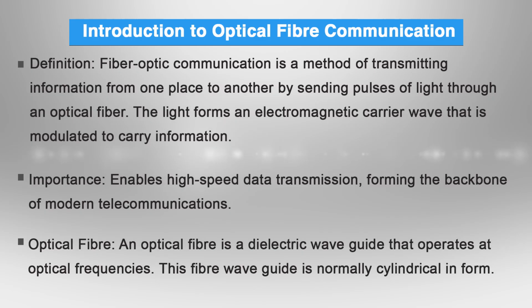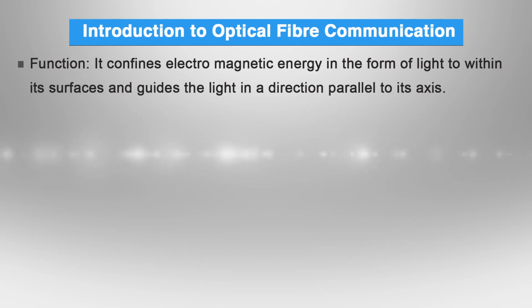An optical fiber is a dielectric waveguide that operates at optical frequencies. This fiber waveguide is normally cylindrical in form. It confines the electromagnetic energy in the form of light to within its surface and guides the light in a direction parallel to its axis.